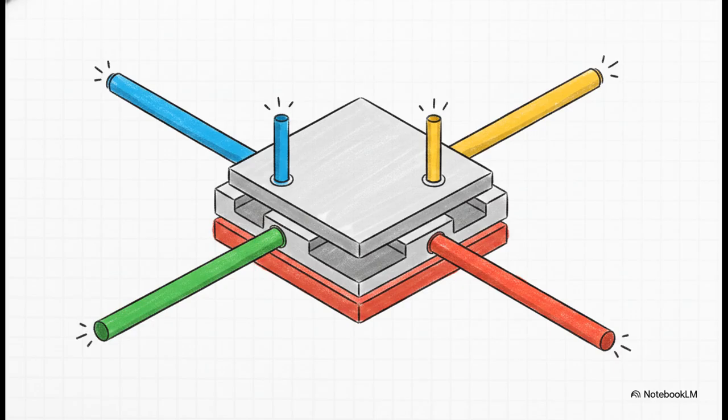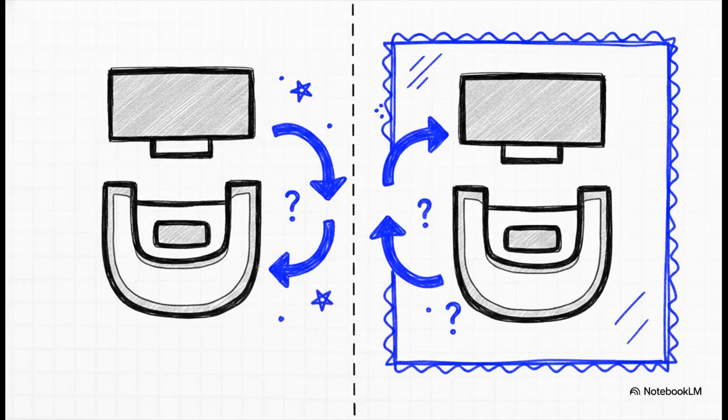Now, I know if you're used to simple 2-terminal diodes, jumping to a 4-terminal device might look a bit intimidating, but please don't let it scare you. It's actually highly logical. One of the absolute most beautiful things about the MOS structure is that it's perfectly symmetric. If you look closely, the source and the drain are physically indistinguishable from one another. This is a crucial difference from older bipolar transistors, which were super asymmetric. This symmetry turns out to be a massive advantage for modern circuit design, giving engineers just incredible flexibility.